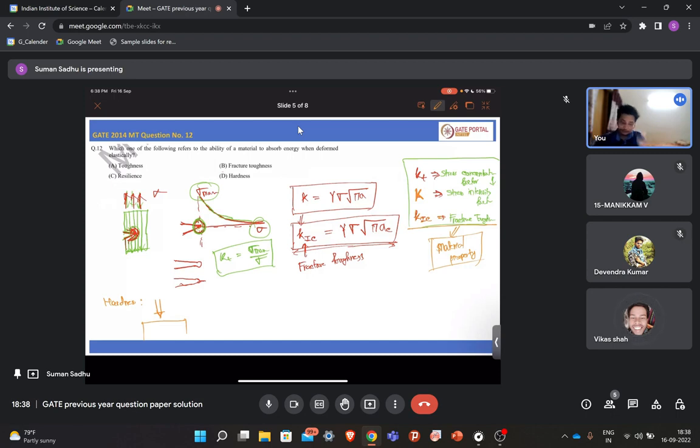So in case of Vickers it is a diamond shape, in case of Brinell it is a ball shape, right? Yeah. So basically you are making an indentation here. In case of Brinell it will be a round, semicircular kind of shape. So you are deforming your material or your sample locally. In a very localized region you are deforming, you are not deforming the whole sample or fracturing your sample. So now we can say what is the definition of hardness.